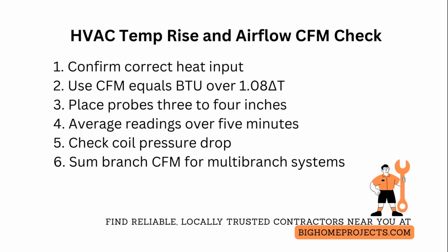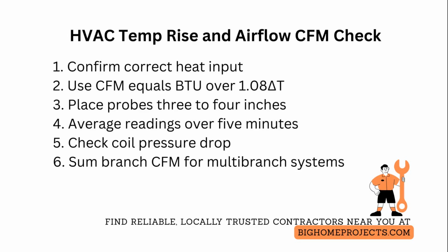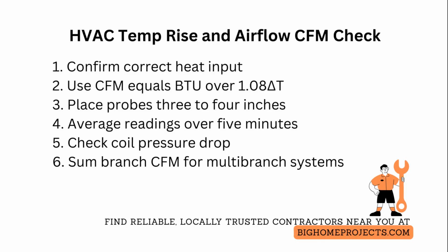Start by confirming correct gas input or electric heat wattage at the unit nameplate, and convert to British thermal units per hour if needed. For gas, multiply natural gas input by 80% only after confirming furnace efficiency from combustion analysis.